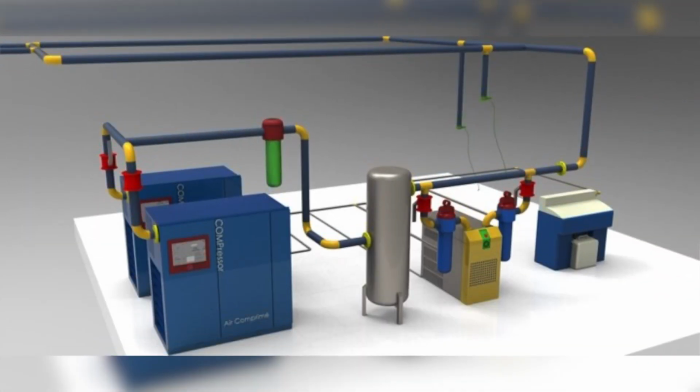Ideally, you should not need to be able to meet the maximum load with any single compressor. You can set your compressors up in the lead-lag model. Let's say that I have my one compressor set at 85 pounds of pressure, and I have the second one set at 80 pounds. The backup compressor will not cycle on until the master compressor can't meet the load and has dropped down to 80 pounds. Some systems use 2 or 3 compressors with different sizes, and you can operate them based on matching of the load. So that's an overview of what you'll see in the compressor room, and your job as an energy efficiency expert is to try and improve operations, either by buying something or changing the operational scheme.